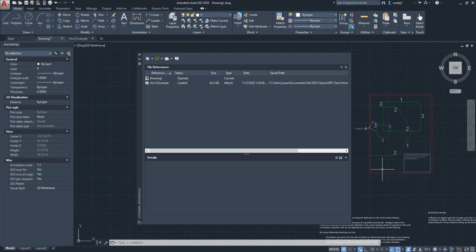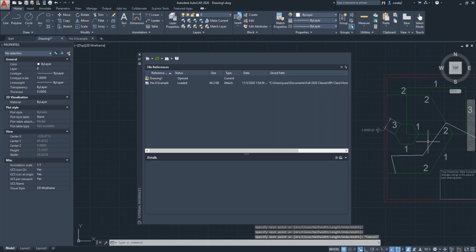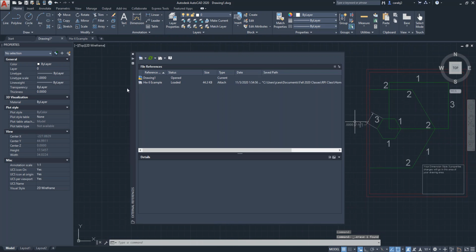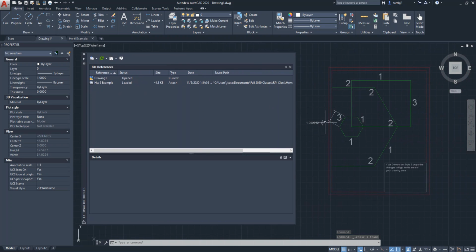It's just an underlay attachment for you. So if I draw on top of it, it's going to show the colors a little bit more vibrant. So that's going to allow you to differentiate between your XREF and your actual drawing working file that you are in currently. So actually, let me just drag this and make this a little bit bigger.